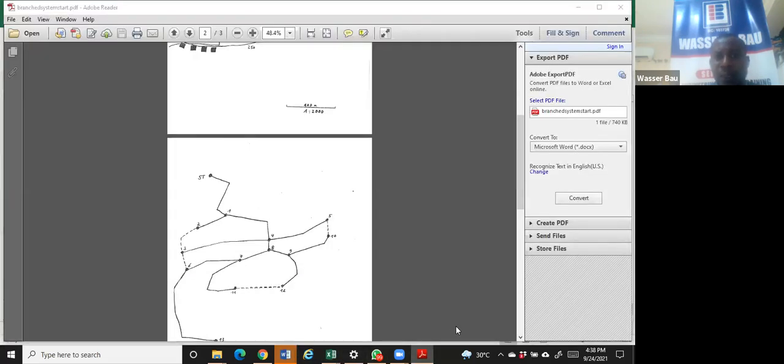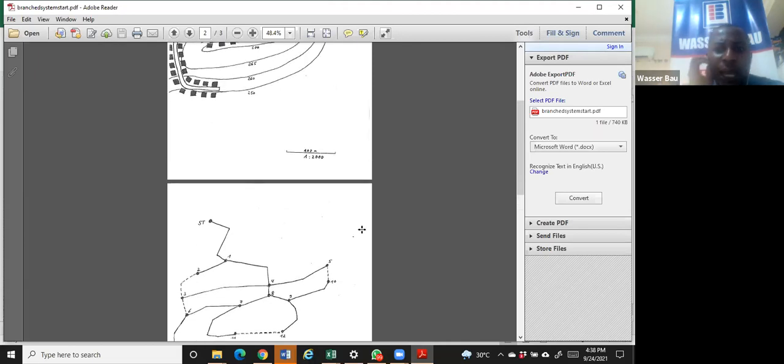So next, I'm going to go to node 10. How many houses is node 10? One of our engineers just asked me, if you don't know the number of houses, then I can choose the area. What area is node 10 going to serve? 2 hectares, 3 hectares, half hectares, 2,000 square meters. How many houses will that translate to based on the land use?